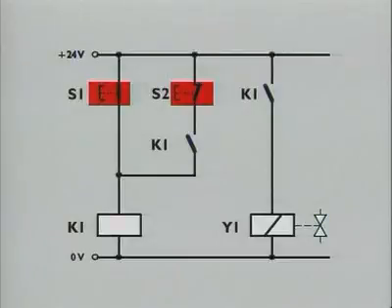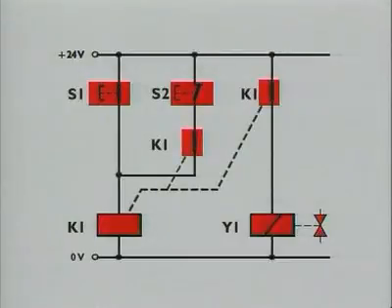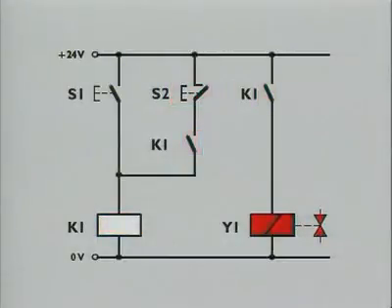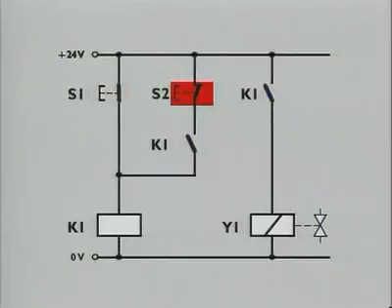When push-button S1 is pressed, relay K1 picks up and the two contacts K1 close. One keeps the relay coil energized and the other switches current to the solenoid valve. This means that the relay remains in this position, even if contact S1 is opened, until S2 is opened. If S1 and S2 are actuated simultaneously, the relay coil remains energized. This is called a dominant on latch.